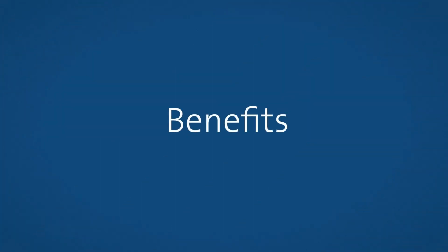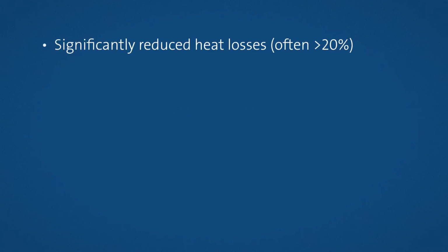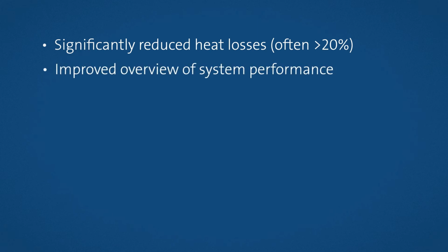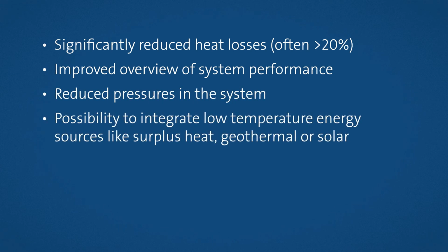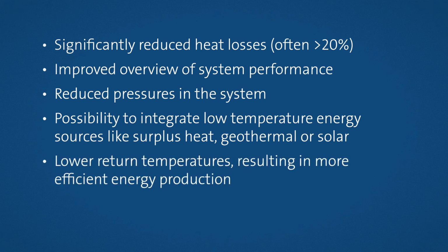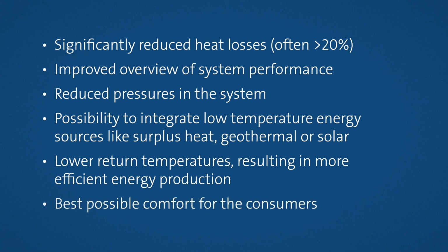Let's sum up the benefits. Significantly reduced heat losses, often greater than 20%. Improved overview of system performance. Reduced pressures in the system. Possibility to integrate low-temperature energy sources like surplus heat, geothermal, or solar. Lower return temperatures, resulting in more efficient energy production. Best possible comfort for the consumers.